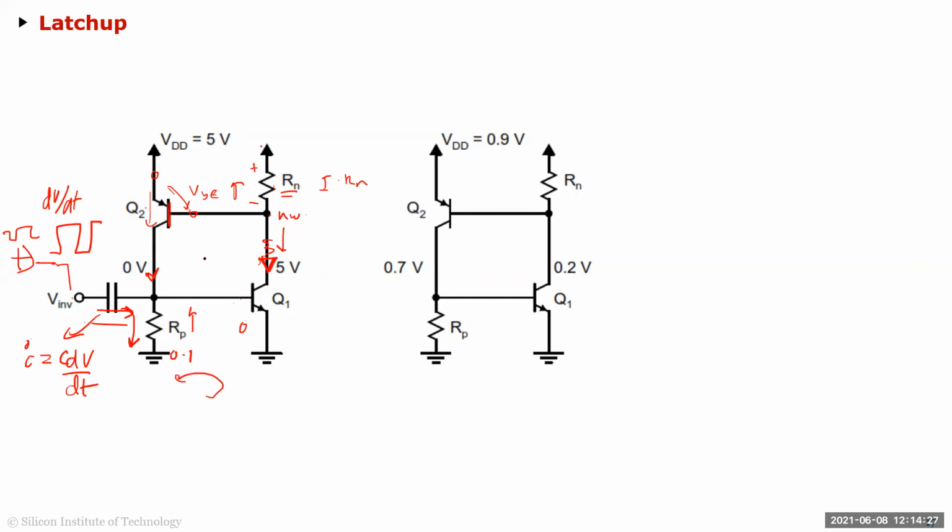And essentially this is like an SCR latch, right? SCR latches are formed that way. And then this will go to 0.7 volts, and you can see then it'll clamp the VDD. I mean, it'll get it down to whatever is the lowest voltage. So let's say the VC was 0.2, this VB was 0.7, then the VDD is going to go from 5 volts to 0.9 volt, but there will be a huge amount of current flowing from VDD to this thing, and it'll basically just fail the circuit. Okay, so most of the circuits actually fail because of that.